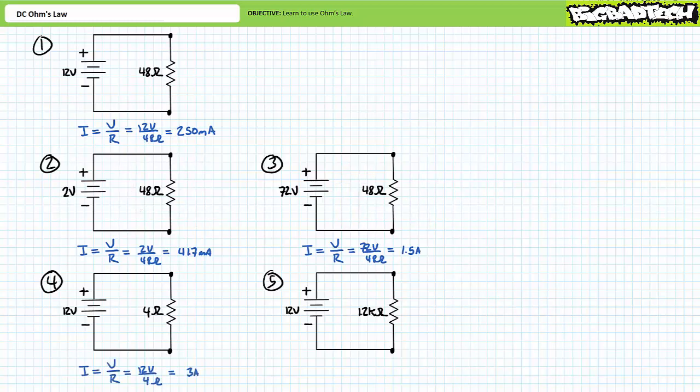Our fourth problem also features a 12 volt source. Only this time it's experiencing much less opposition in the form of a 4 ohm resistor. We're being asked to solve for current through it. Current is voltage over resistance. Ohm's Law demonstrates 12 volts over 4 ohms of resistance yields 3 amps of current. Although we're still using a 12 volt source, this circuit experiences substantially larger current through it than our first one because the source sees much less opposition.